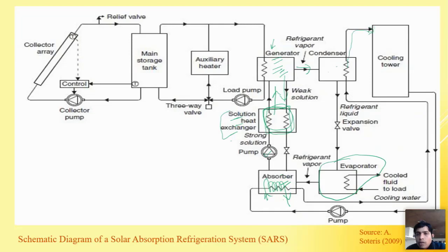In the cooling tower, what happens, probably you all know, but still I'm explaining this. In the case of the cooling tower, we actually make a pipe arrangement and spray. Multiple spray systems are used, okay, which actually convert the drop into very small drops. So there are multiple things that happen in the cooling tower. So first is splitting of one bigger drop into multiple smaller drops.